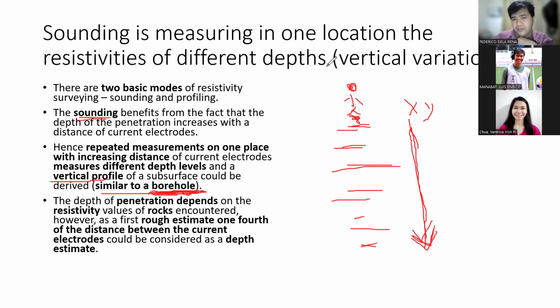If you have a borehole at this point and a borehole at this point and you want to know what's in between them, you can do many resistivity surveys between those two points, and from there you have a better understanding of a large area, for a cheaper price.